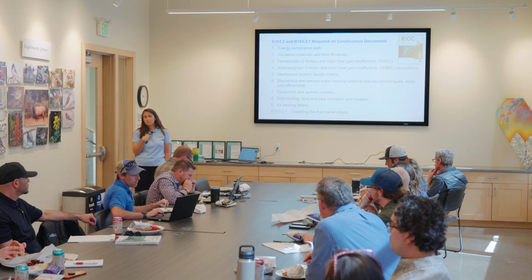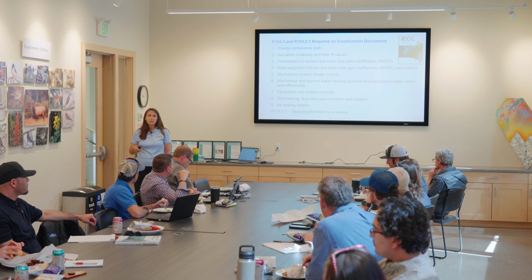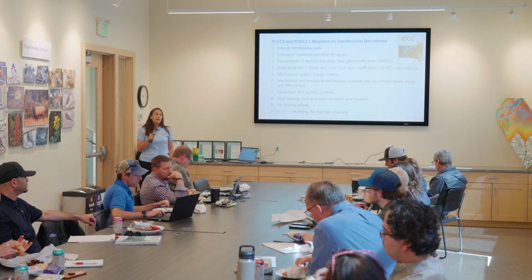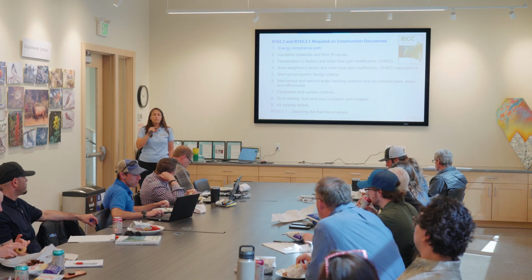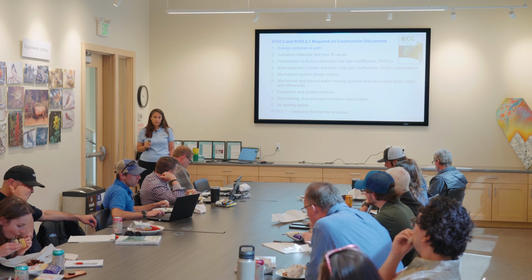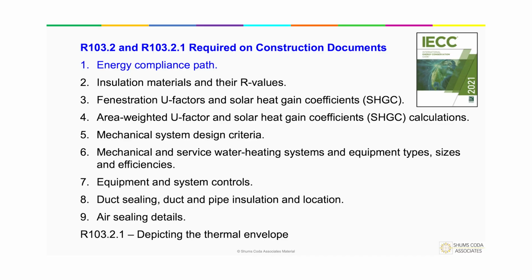If it's a plan that comes to me, I can guarantee you I make them put those notes on the plans so everybody's aware of it, especially if they have those ducts and piping that's going to be outside of the thermal envelope, they're going to put that on there. If it happens to be that everything's inside the thermal envelope, then I don't worry about that other than the duct sealing. But I do want this information placed on the plans, and it should be in accordance with all the information that we have here.